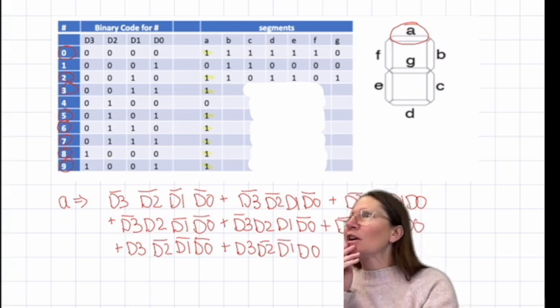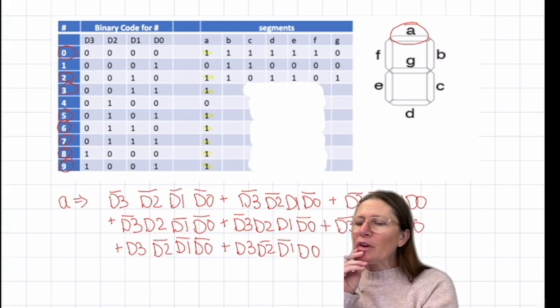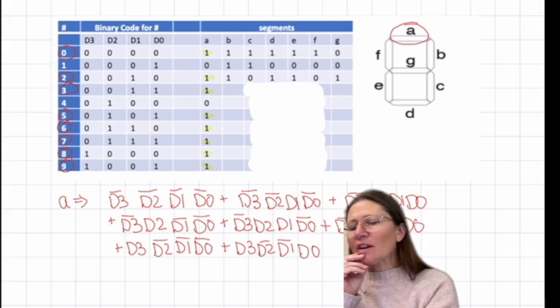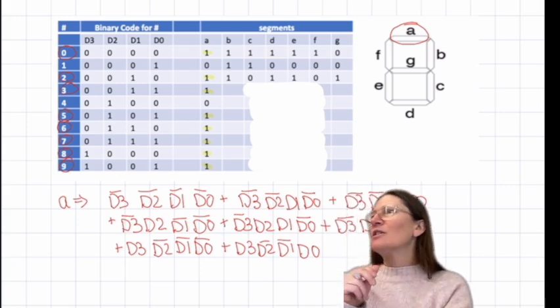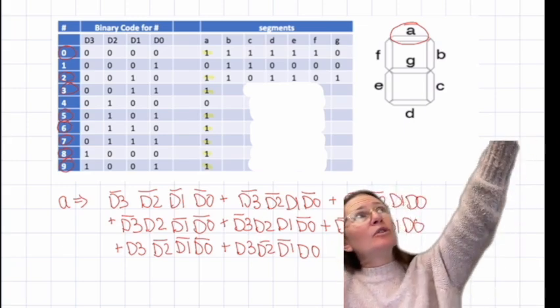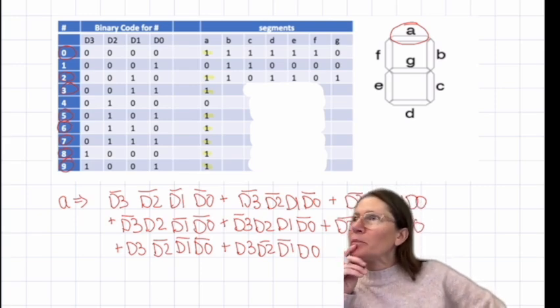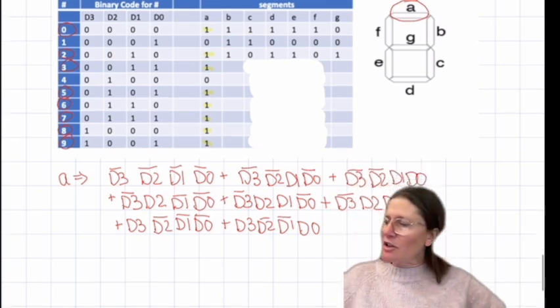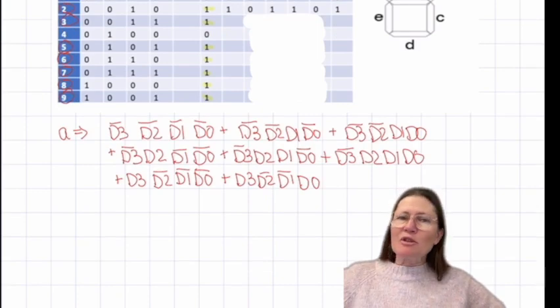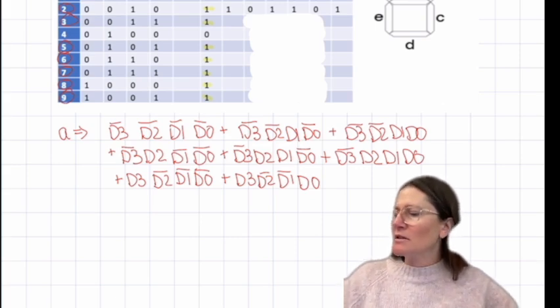You'll want that on when it's a 0, 2, 3, 5, 6, 7, 8, 9. So you could create the truth table for each segment of the display, and then create logic from it. You can reduce down the logic a little bit by noticing terms.